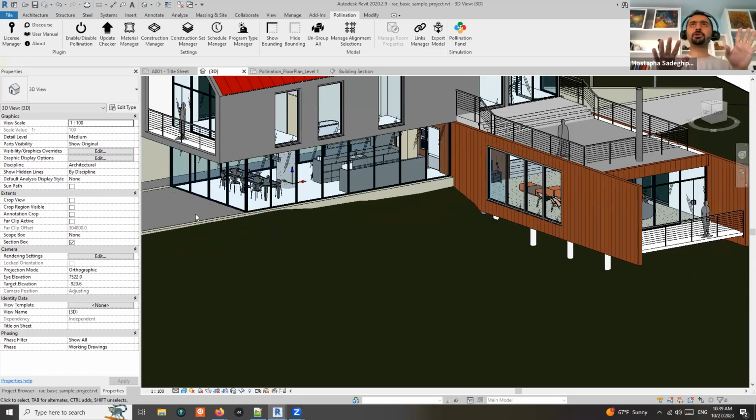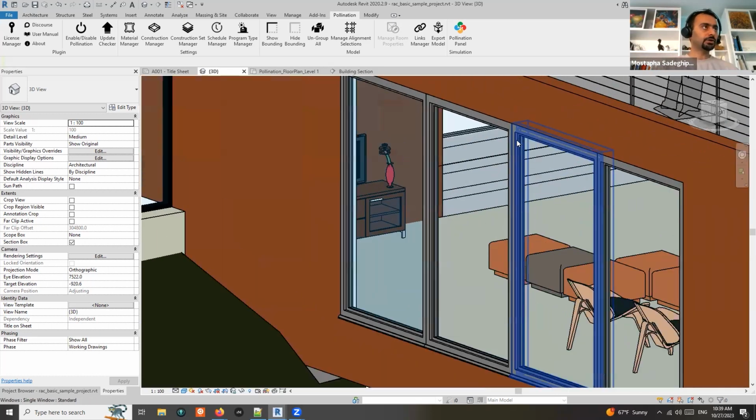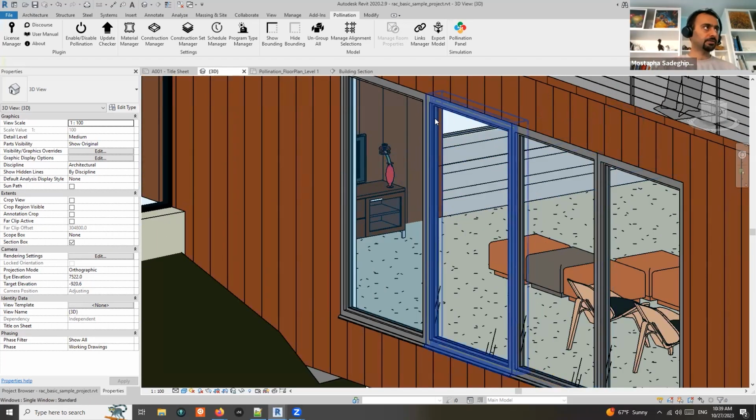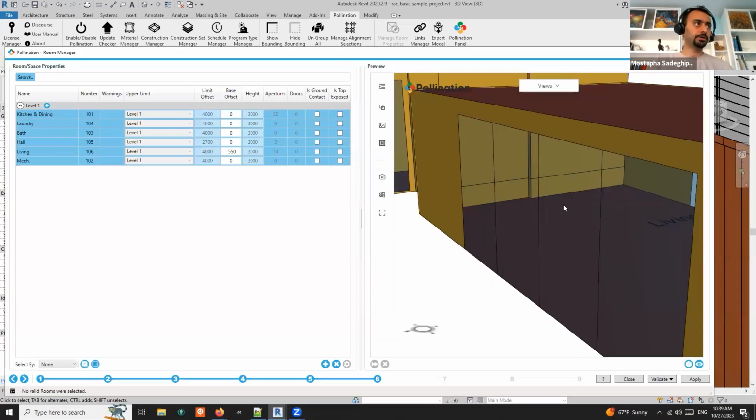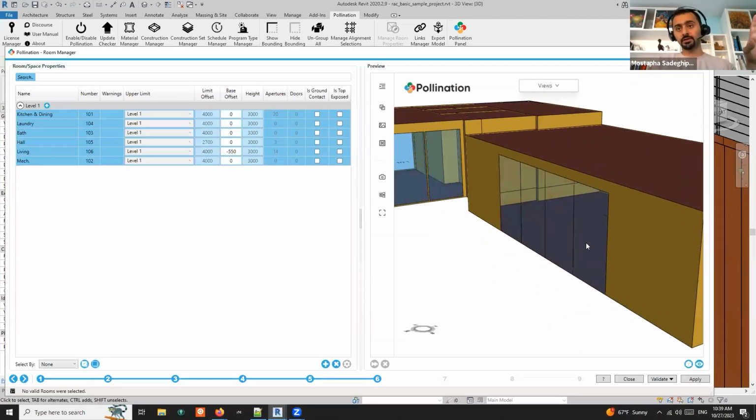Because you will get people doing so many things with curtain walls, right? Sometimes things that they shouldn't even be doing. But in this case, as long as you select the curtain wall panel, it will be exported. But for windows, you see the frame was also included. Otherwise, if it was only the glass, it should have just stayed inside, right? So again, this comes to how you want to prepare your model. Some people think this is fine. Some people want only the glass and then they want to change the U value to include the frame. Some people do this and then add the frame somewhere else. All these things are options. But what I'm going to show you is you have the option.